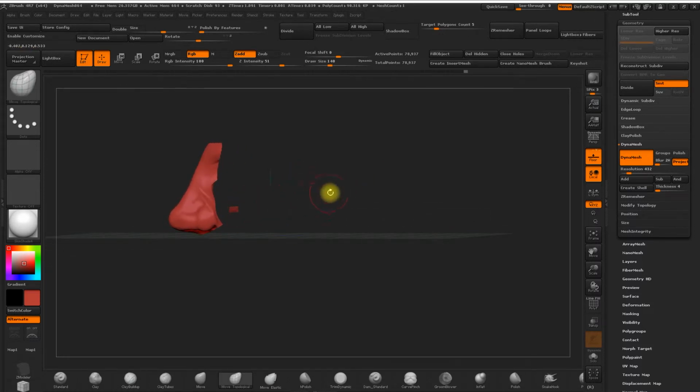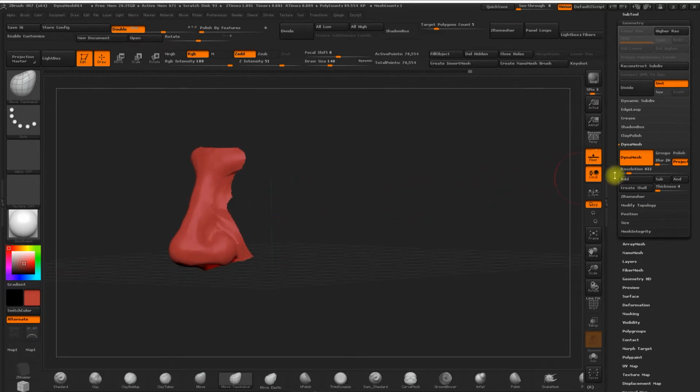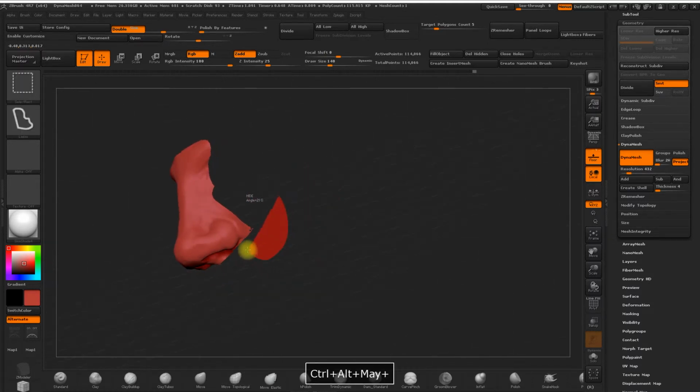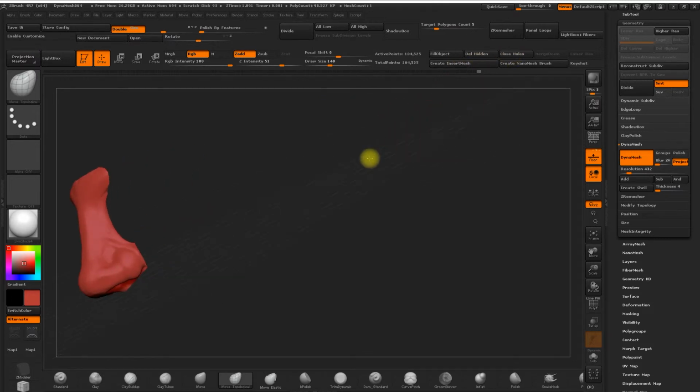Sometimes you'll get parts of the model that we can't see. To solve this, we'll activate this box. We'll select the double button. Now we can see this element. And now we can make another DynaMesh to update the mesh and then soften this part. Or just eliminate it. Like that. With hidden close holes.